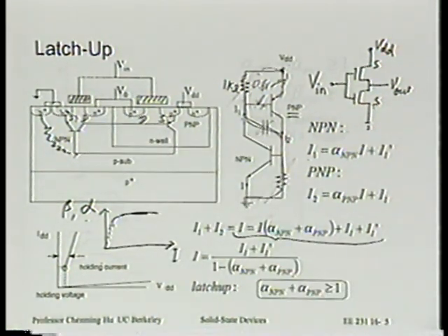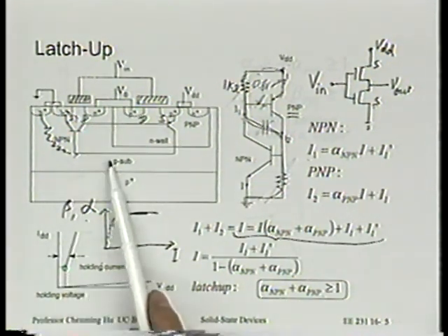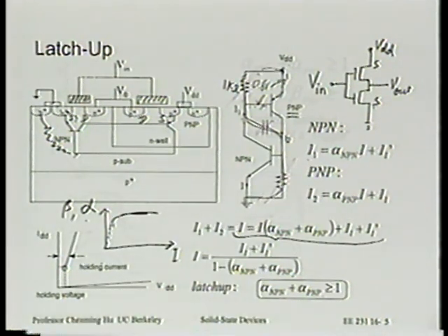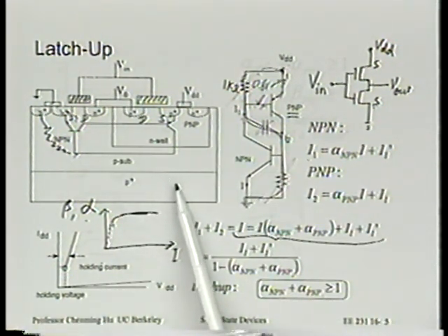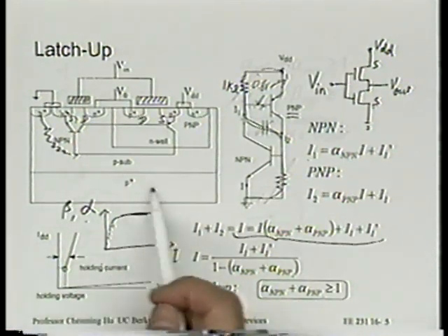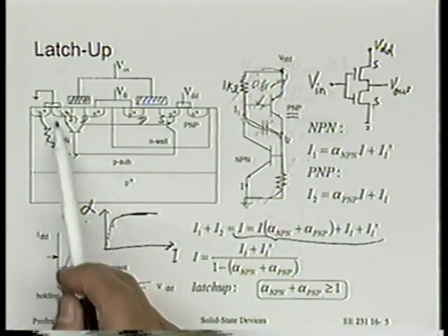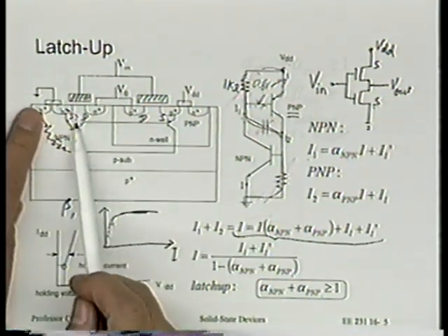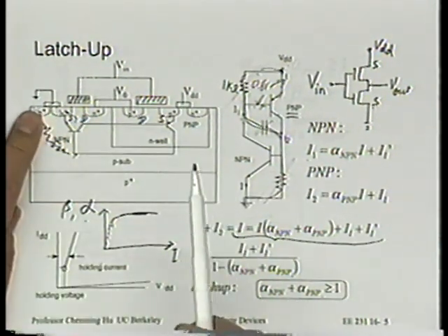All right? And other times, people will build a circuit on a P plus epitaxial substrate. And you pay some more money when you order the substrate, but it will give you better latch-up behavior. Why is that? Because this P plus material helps short out this resistance. See that? Okay? You have to remember, this is not drawn to scale. These separations could be tens of microns, right? Between where you have the contact and the farthest transistor somewhere, right?